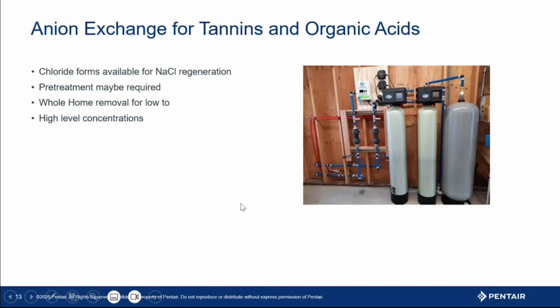Now, for anion exchange for tannins and other organic acids. If you're targeting PFOAs, make sure you use a material designed for that. But if you're targeting tannins, tannin resins are available in chloride form, so you can use them or even share a brine tank with a cation softener if it has its own well system inside of that brine tank.